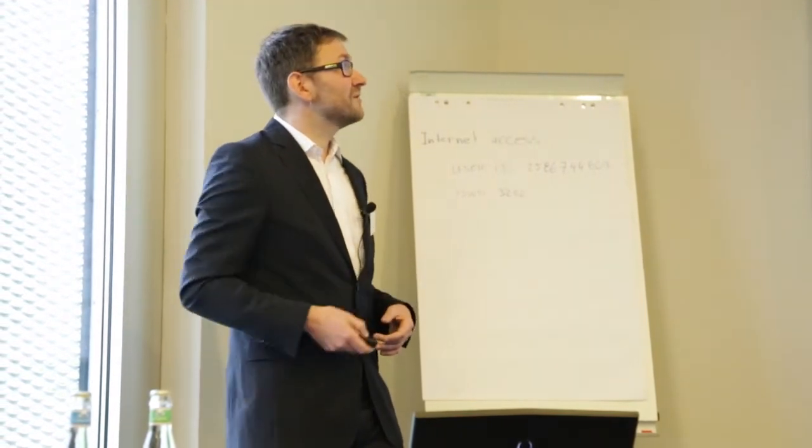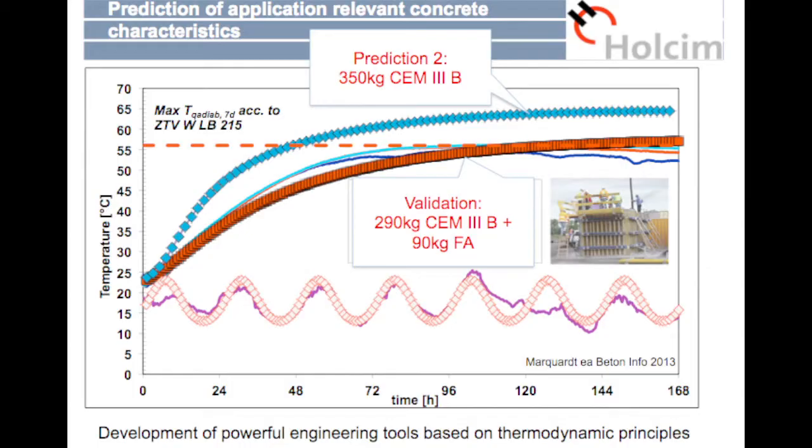Based on these results from 2008, we got the experimental data, and we could obviously use it as a benchmark case for our software. I'm not going into details with the software, but if we employ all the boundary conditions that we had on site, and we take the calorimetry data from the quality control in Germany, that means we have our kinetic model and our heat model. So we could derive a very nice agreement between the experimental data and the measured data.